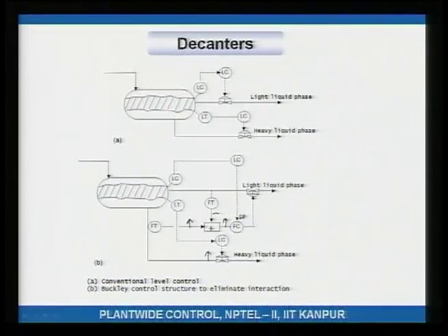If this flow goes up, in order to maintain the total flow, which is this guy, if the total flow has gone up and I want to maintain the total flow at set point, what will this flow controller do? This flow controller will close this valve. As it closes this valve, this guy goes down. Because this guy goes down, total flow comes back to wherever it is supposed to be, right.